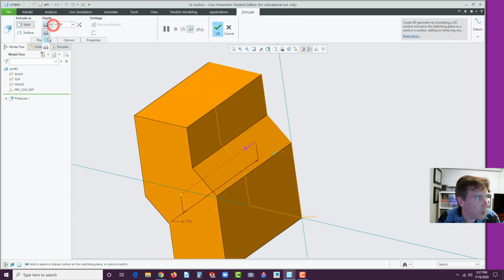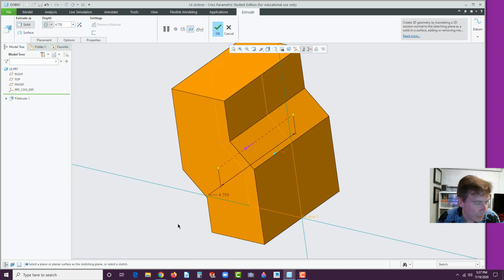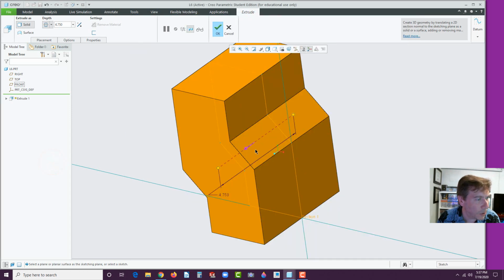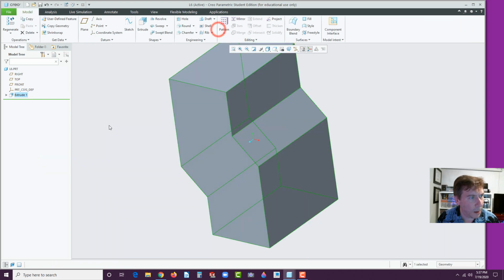Let's go mid-plane. And you would think I would be better at doing this. I do this maybe once every couple of years. These were models I made, so my bad. I should have practiced it that time. So we see it's 4 inches across here. So I'm going to go mid-plane, 4 inches, hit apply.